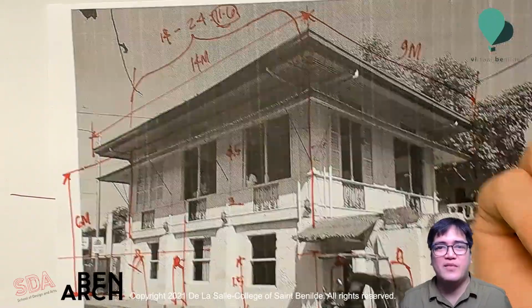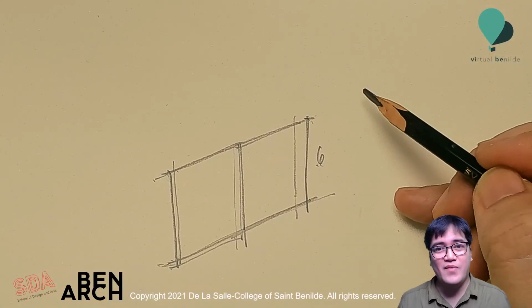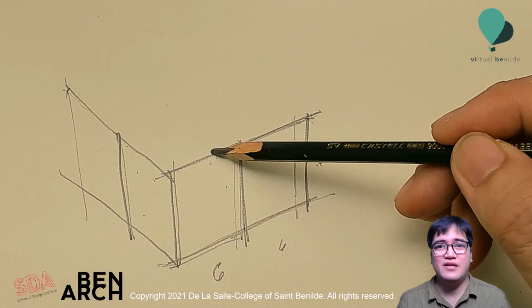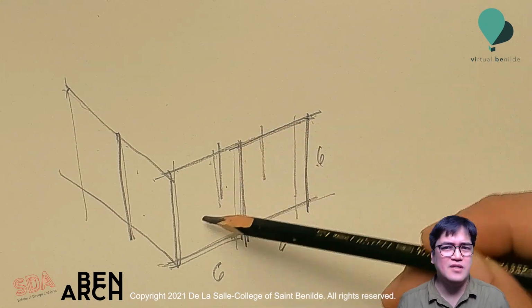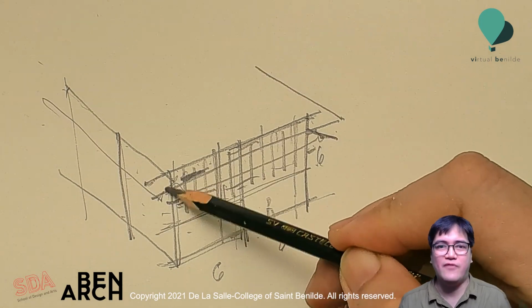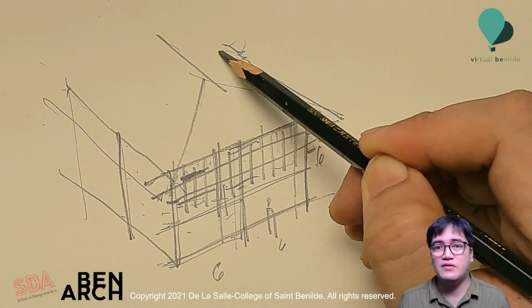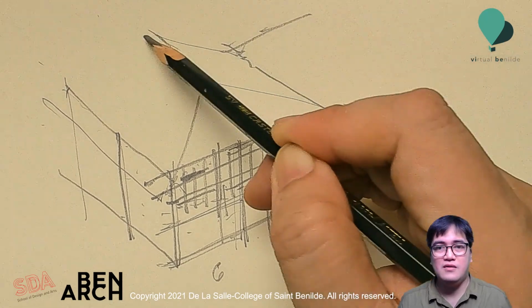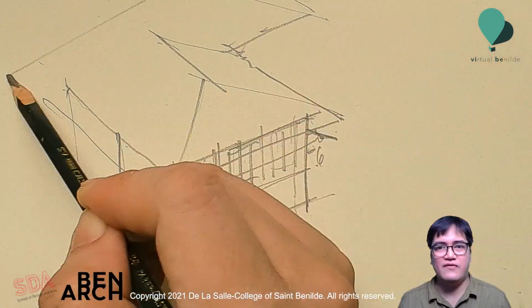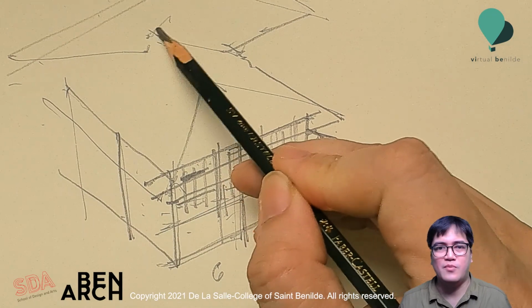Now you can approximate the height of the levels using, again, a small piece of paper and mark up the relative vertical line. So in the case of this example, I have determined that the facade of the house is about 6 meters high, 12 meters wide, and with a 14-meter front roof edge. The eaves of the roof are usually 1.2 meters from the wall, and I have just rounded off the offset from the walls to something like 1 meter, just to simplify things.